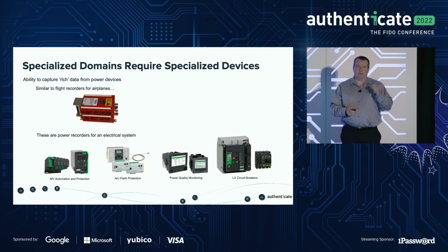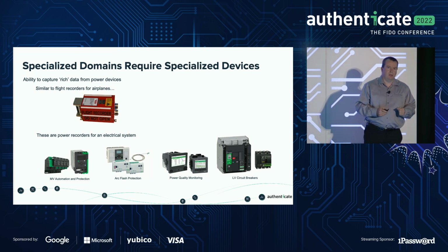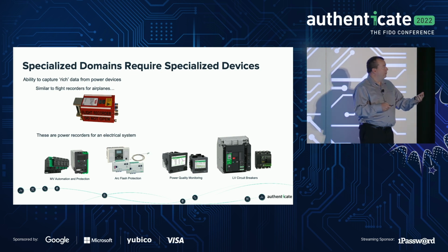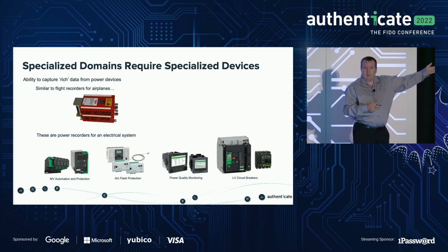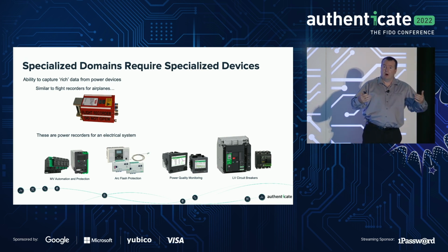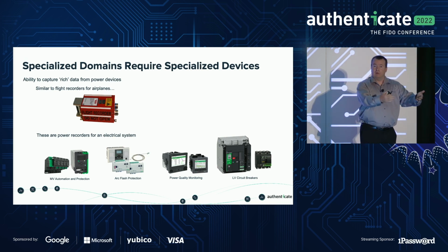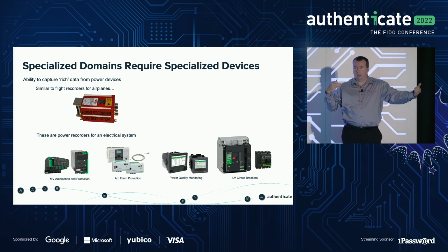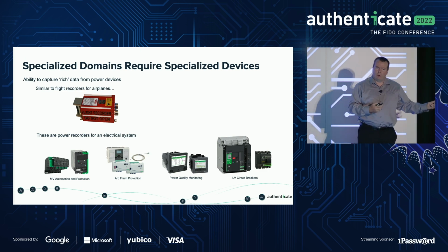They're not like the circuit breakers in your house that just trip when there's an overcurrent condition. It's much more complicated than that. These are similar to PLCs, but in some cases even more powerful. You'll notice some medium voltage. By the way, medium voltage to us is in the thousands of volts, right? So medium voltage arc flash, so now we're talking about safety. Arc flash is when there's some type of a short on the electrical network and it's possible that a person is too close and they experience that molten metal, right? So it's a safety condition. Power quality monitoring, talking about harmonics, noise on the wire.